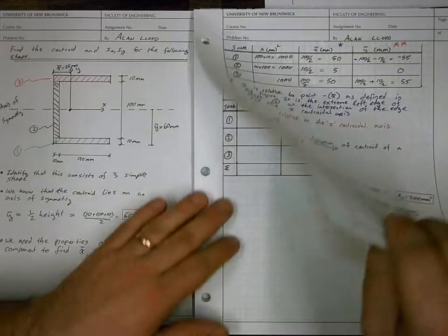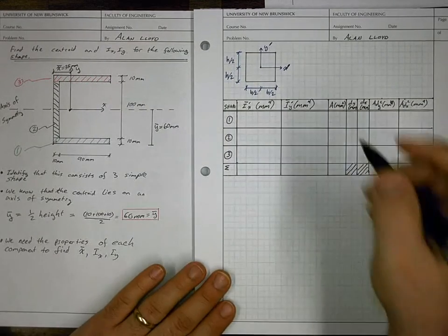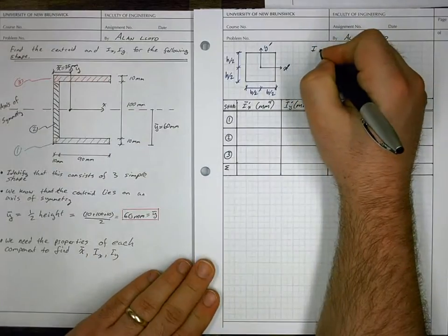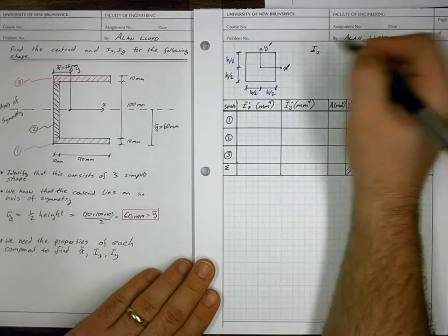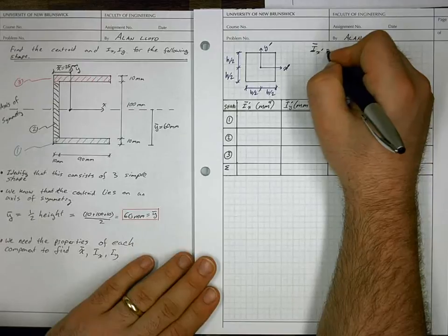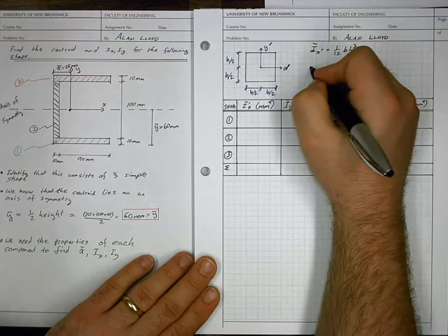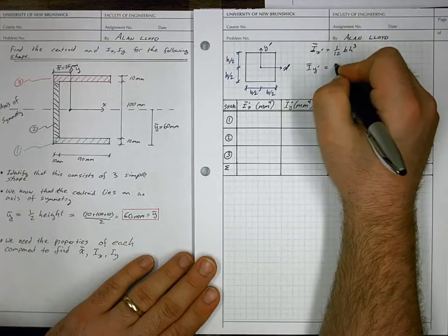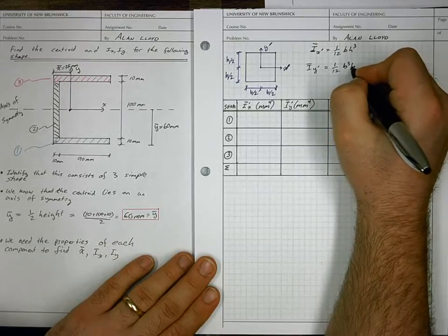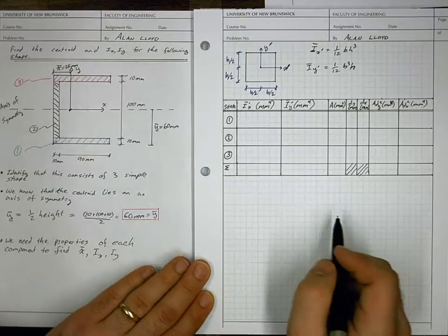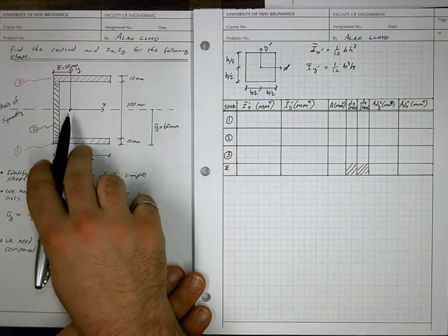In the parallel axis theorem, we can state that for each subcomponent, first of all, if we look at a rectangle, I bar x prime is equal to 1 over 12 base times height cubed, and I bar y prime is equal to 1 over 12 base cubed times height. And then later, if we want to determine the moments of inertia about the global x and y system, we can say